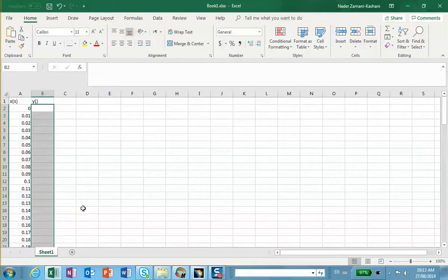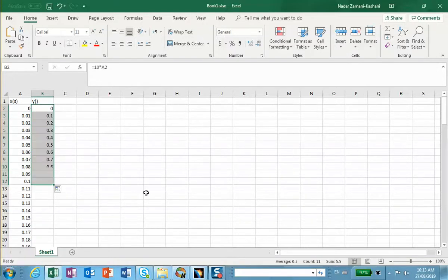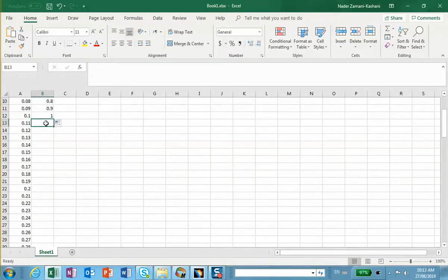So this is equal to, let's say 10, and where I get 10 is, let's say the first 0.1 second, the first 0.1 second times that. Hit return. And then drag this thing, go all the way to 0.1. So you can see the first 0.1 second, the load is applied linearly. And at this point, my cosine will disappear.